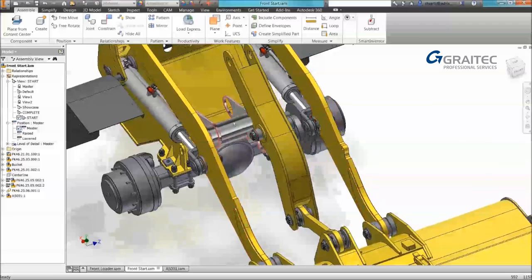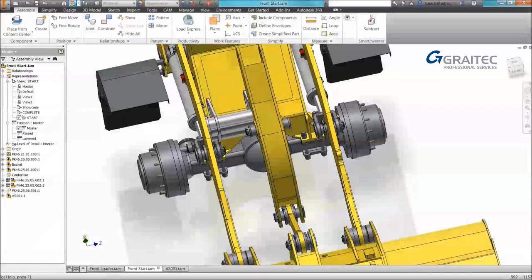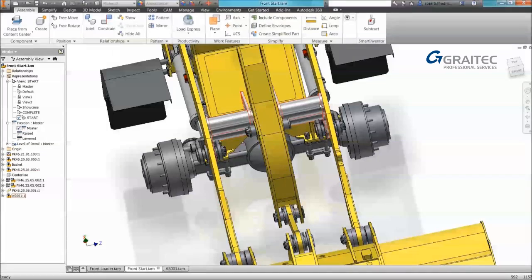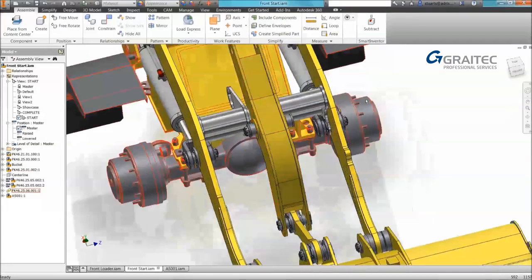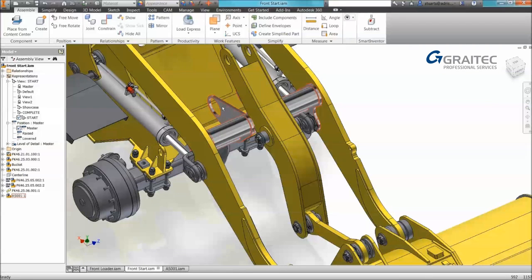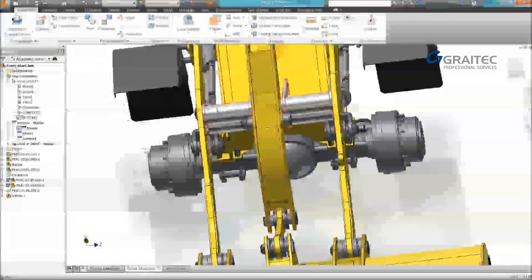So it still hasn't quite updated, we can still see it's the same. All we do is do a local update of our assembly and it will refresh our components, and you can see it's now changed to the size it should be. So one of the advantages is we have a central file that can drive and change all of the components, and we don't have to worry about constraints because everything's modeled in place. So that's multibodies, or an introduction to multibodies.